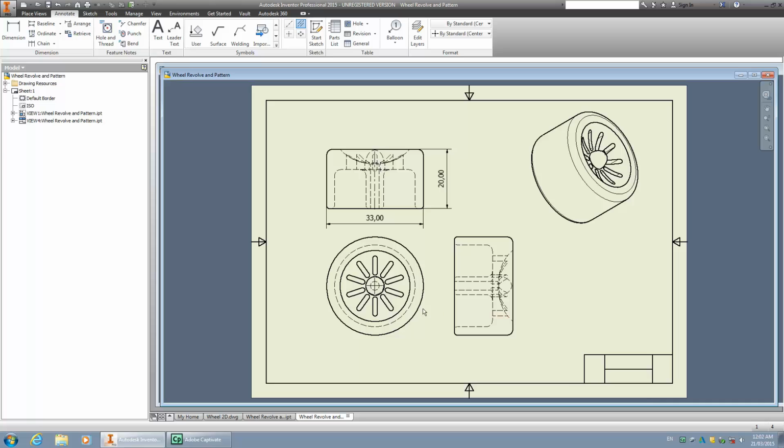So there's heaps of possibilities for you. You can create diameter dimensions. So we're still on the dimension tool, I'll left click on dimension over here. I'll create a diameter dimension. Now if you don't like this diameter dimension and you want a radius dimension, just right click and go across to dimension line and click radius, and you'll find yourself with a radial dimension. So you can choose diameter or radius as it suits you.